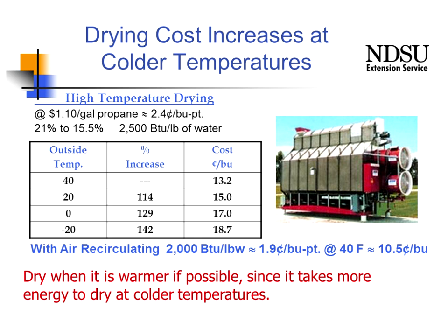One of the things that sometimes I think gets overlooked is that the colder the outside temperature, the more it's going to cost to heat that outside air, and the more expensive the drying becomes. And so this needs to be balanced against that first slide where we talked about leaving the corn in the field to dry down.